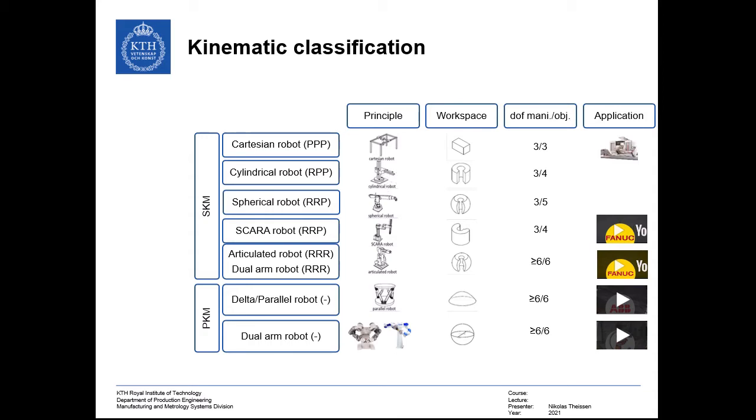And here you have a serial chain of those joints, meaning that you have only one way to read those letters and start from the base and arrive at the mechanical interface. For parallel kinematic machines, this isn't possible because you have several actuators acting on the same link, meaning that there is no simple way to read yourself in terms of actuators from the bottom to the actuated side.